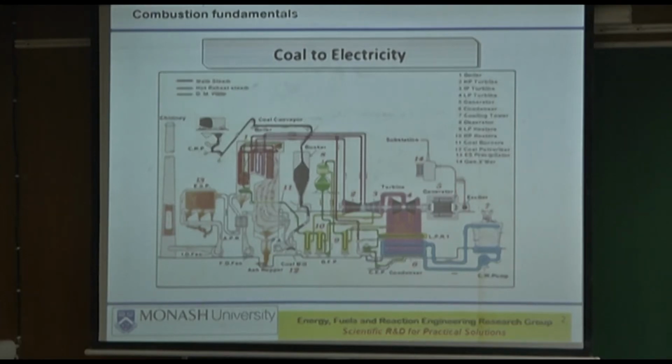Unless it is a very unreactive anthracite kind of coal, which will not work well at all with this type of burner arrangement, this is very well known. You give them the coal composition and the coal rank, and the technology developers will immediately tell you, I'll choose this design, not that design. It's that simple. It's very well known now, because there are 50, 60, 70 years of history behind it.